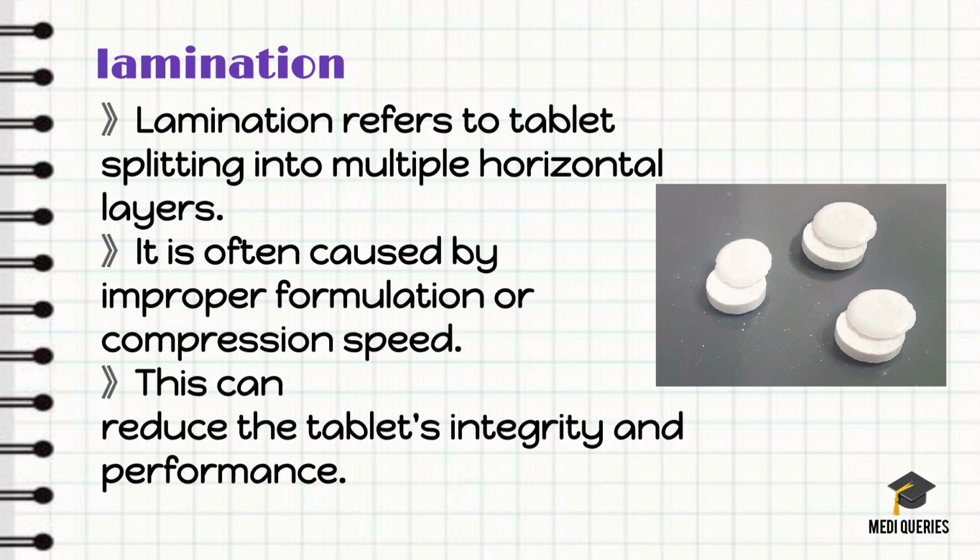The layered separation may happen during ejection or even during post compression drying. Improper granule size distribution or over dried granules can also lead to lamination.